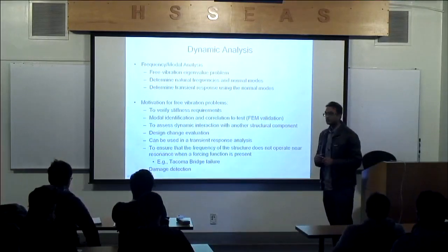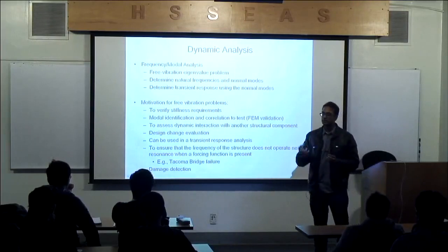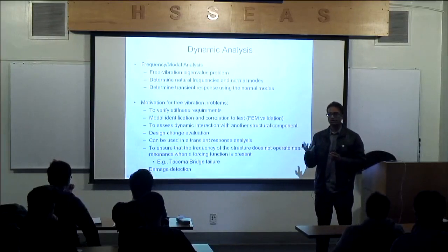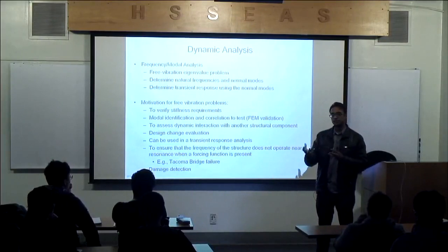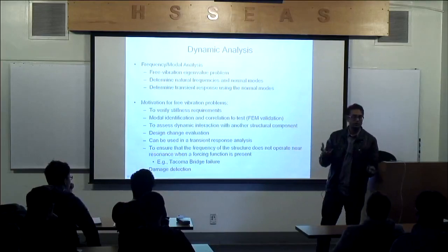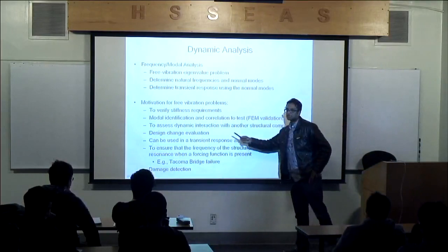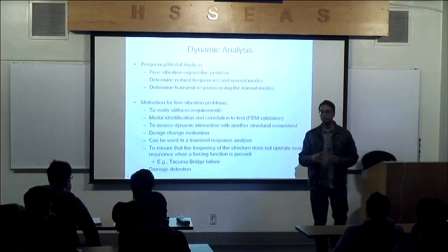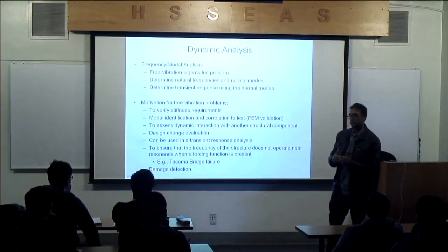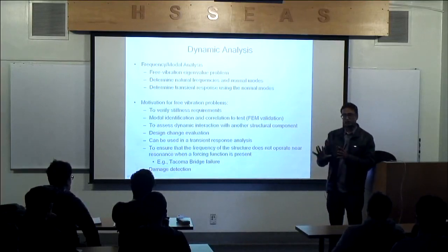We can assess whether there's a dynamic interaction between one component and another component. For example, I could have a resonant condition where one component is vibrating, but it causes another component to vibrate excessively. I could also look at evaluating design changes. Maybe I want to prevent exceeding a particular frequency of concern, then I want to stay away from that frequency range, and I will have to design my structure to allow for that.